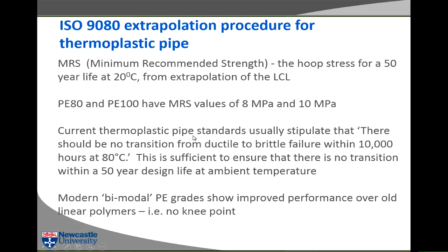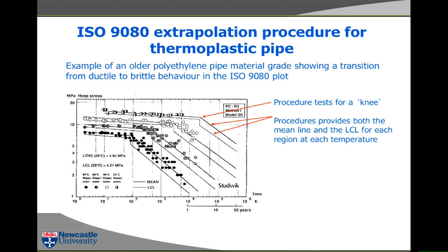Another thing that you need to remember is that the pipe standards stipulate that there should be no transition from ductile to brittle behaviour within 10,000 hours at 80 degrees C, which is what you have here. So there's your 10,000 hours. Sorry, 10 to the 4th. There's your 10,000 hours. So that must not happen